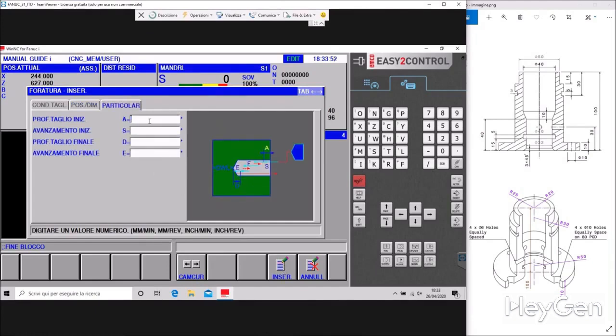Now you want the drill bit to enter smoothly for the first 5 mm. We set a feed rate of 0.13, but I want it to start at 0.06 per revolution for the first 5 mm. And at the end, because in this case I'm crossing another hole, I want the last 5 mm to also exit at 0.06. I said 0.06, but I set it to 0.05 just because I mentioned it. Let's modify that, so the last 5 mm drop the feed rate back to 0.06.